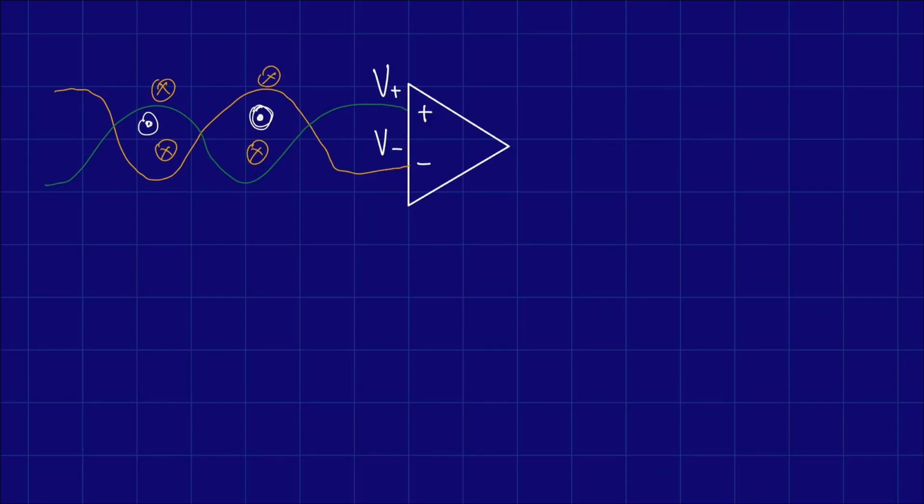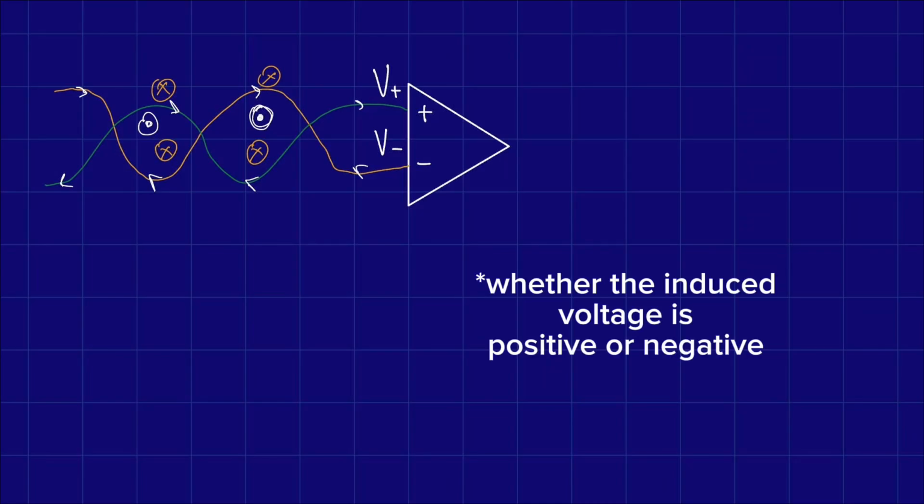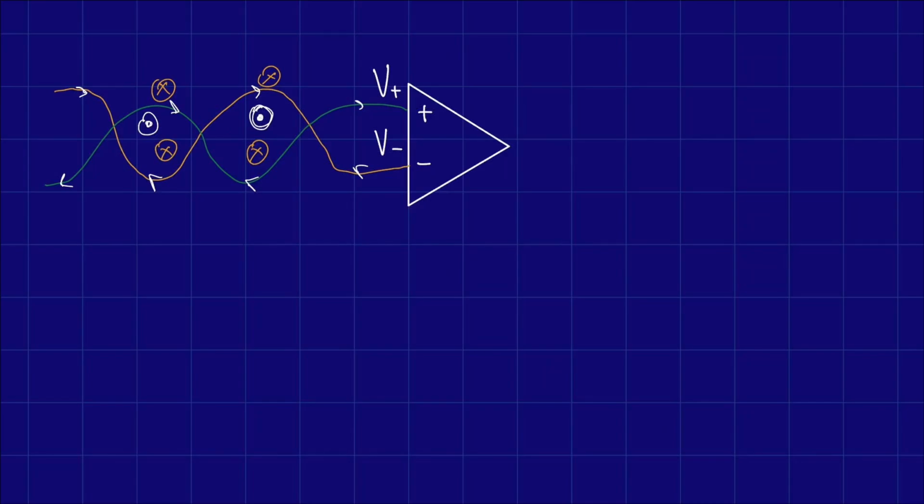That will be, in this case, if you do the right hand rule that I taught in the other video, the currents will go like this, okay? And the magnetic fields are already here, and I still drew them in order to understand the direction of the induced voltage. But remember, the currents and fields do not exist here. It's just a convenient way to prove to you that there was an induced voltage. After I understand this, I will delete the induced currents and magnetic fields so you don't get mixed up. And the important thing is that you just continue to focus on the induced voltages, because those are our actual disturbances and those are real.